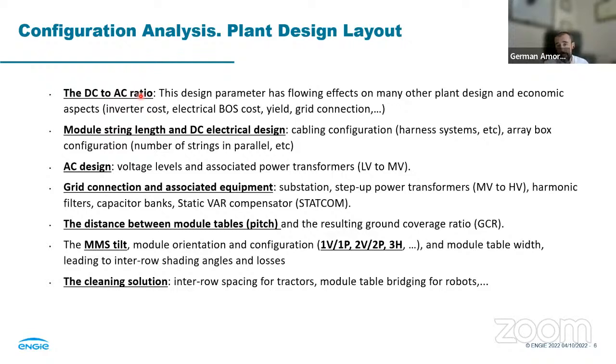And obviously we have a maximum DC that is in the administrative process that we have declared to the administration. But this is an important topic for the DC/AC ratio, because otherwise we don't have sufficient power to comply with the capability of reactive power capacity at the point of connection, according to the active power declared to the TSO, transmission system operator of the country.